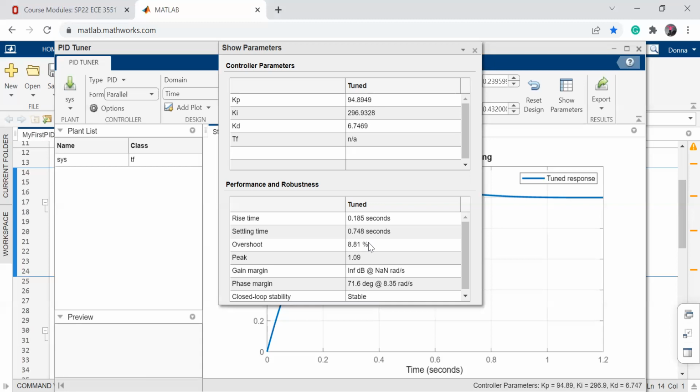You have to apply it to a system, so code, and then run a voltage generator or current signal generator system. Let's look at how it looks. It took more than 2 seconds. So then on the hardware, you will tune. That's the refinement idea. Tuning has a few steps: first theory, then go to simulation and try to find the common sense, then hardware in the loop and make sure that it still satisfies all the requirements.